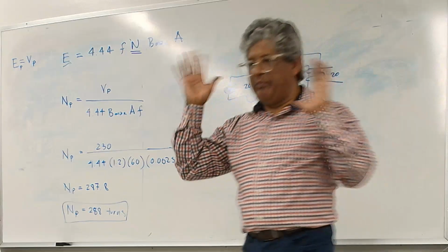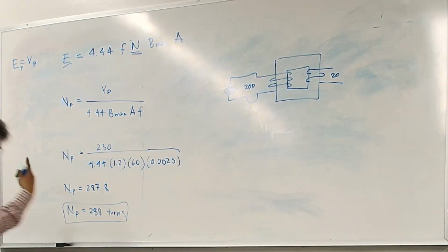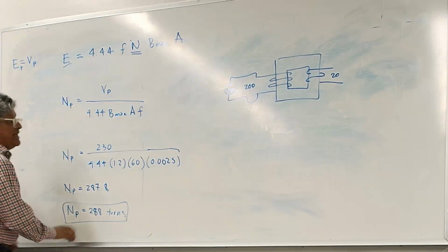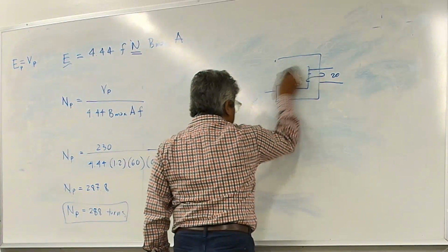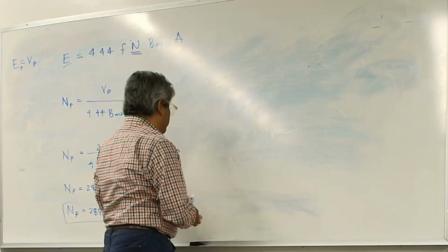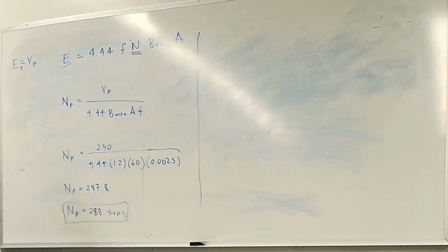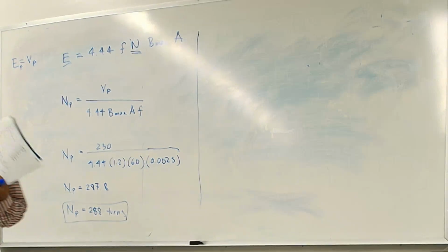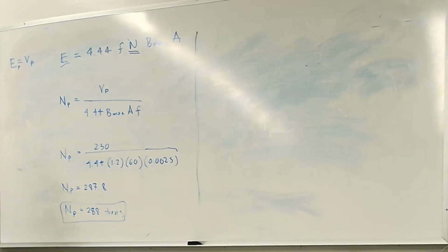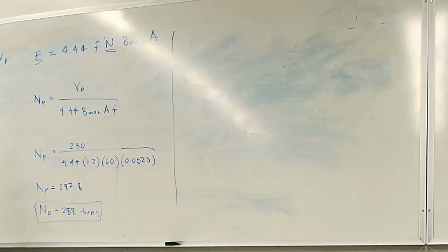So anyway, do I make sense, everybody? This is just giving you, once again, the people that I see using this equation are protection engineers when they're looking at the saturation of current transformers. They use the formula method sometimes because they have all that information. They just want to know, am I going to saturate this CT or not? For them it's really important because if you saturate, the relay doesn't see the current that is supposed to be seen.